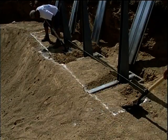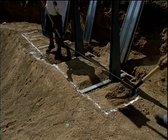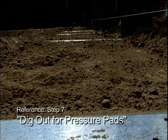This area should be dug out to the side stakes. This is 24.5 inches from the center of the outer ground channels. The trench should be 2 inches deep from the pool floor and level with the ground channels. Please reference Dig Out for pressure pads.